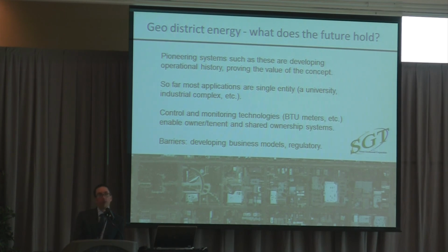So there are ways to gradually transition from a steam or chilled water system, and that's one of the things that we're looking at at Weber State. One of the design challenges here for sure is taking an existing central plant system and transitioning it. If you could flip a switch, it would be a lot easier, but the challenge is to transition it so that all the components continue to work through a potentially decade-long or longer transition. And there are ways to do it. Ball State, the biggest system that I mentioned, has done that. They were a typical old school steam plant, and that's part of what they work on.